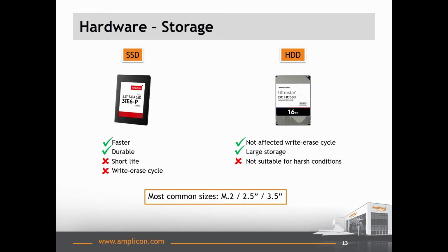The size of the system and the amount of SATA ports or M.2 slots will limit how many drives and of what type. If you require terabyte upon terabyte of storage, you need to look at a rack mount solution, not embedded. My recommendation for most systems is to put the operating system and any software on an SSD and have a hard drive for storage. This allows you to leverage the speed of an SSD, but have the mass storage capabilities and low cost of a hard drive.